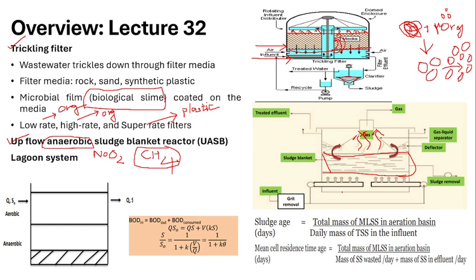Okay, and wherever the sludge is not entirely solid, it will be a solid-liquid sludge, and now it is also producing gas, right? So this gas-liquid is separated, and the pure biogas is collected from the top. Finally, the treated water is collected from the tank. So this is how the anaerobic sludge blanket reactor will work.